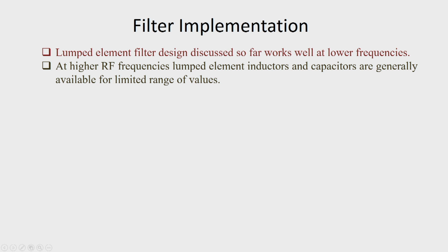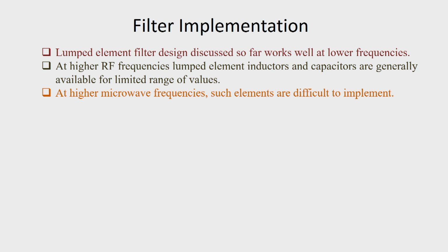So, lumped element design discussed so far works well at lower frequencies. At higher RF frequencies, lumped element inductor and capacitors are generally available for limited range of values. At higher microwave frequencies, such elements are difficult to implement.